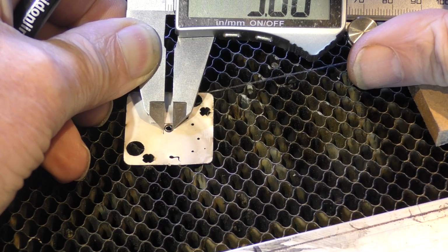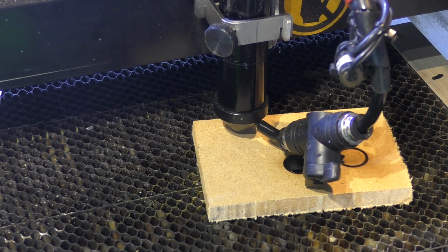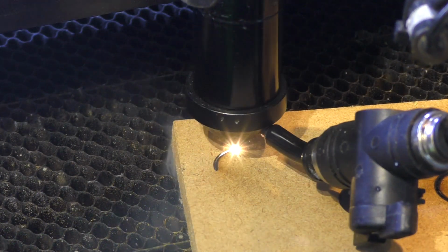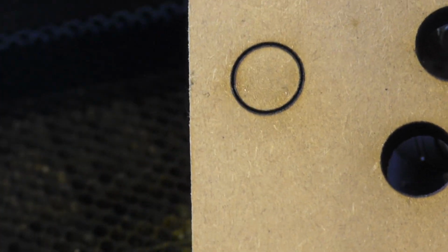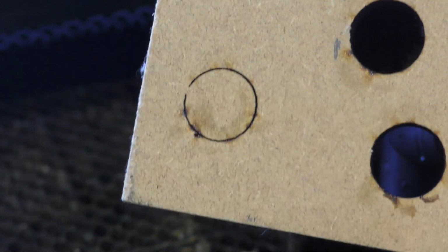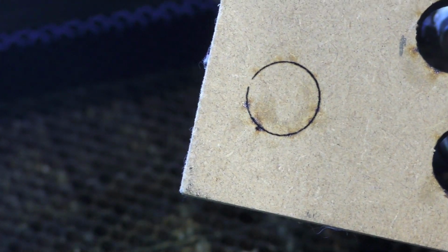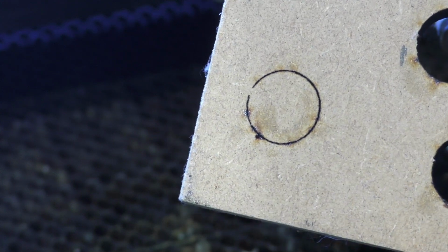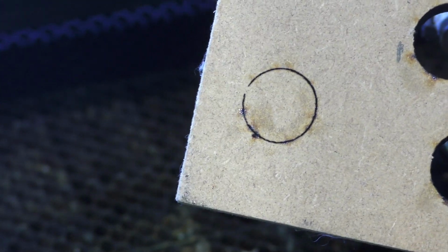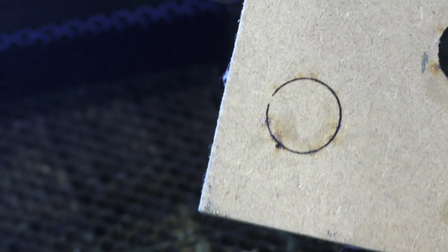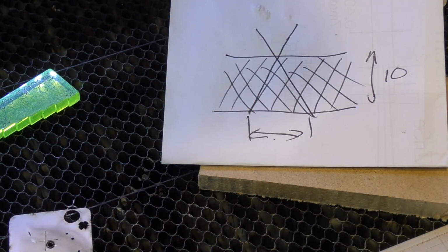It's about 3mm diameter as it exits the material. And this is at full 70 watts, but we're using 4mm a second. Even though that was where we supposedly set the focal point. And underneath, well, yeah, we've got more or less a cut. It's not a complete cut, but it's more or less a cut. Hang on, stop. What thickness is that cut as it comes out the bottom? I'd say it's about 0.1 or 0.2. Not 3 millimeters. Lens theory predicts something different.